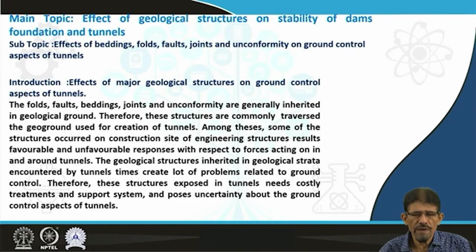Due to adverse effect of geological structures, the tunnels require costly treatments, complicated, advanced and costly support system to encounter the problem concerned with effect of these geological structures. Hence, we are going to face the cost of treatment as well as the technical uncertainties during development of tunnels.